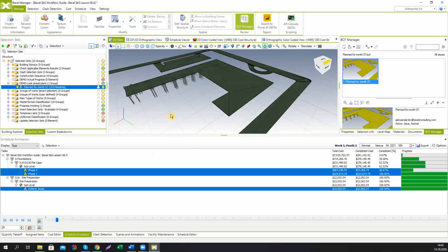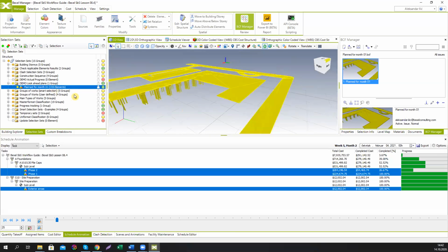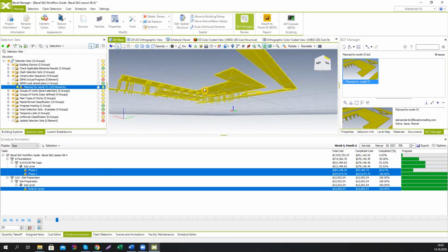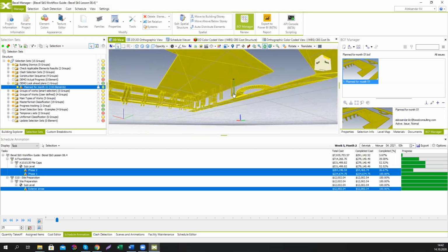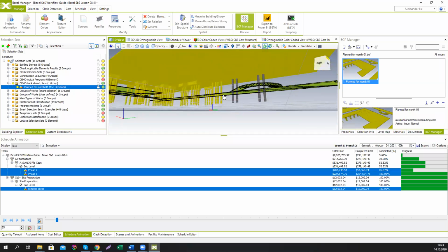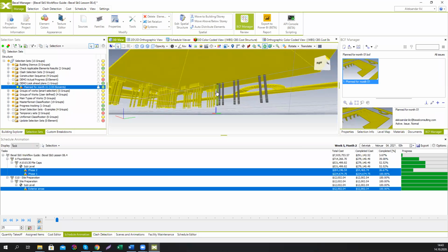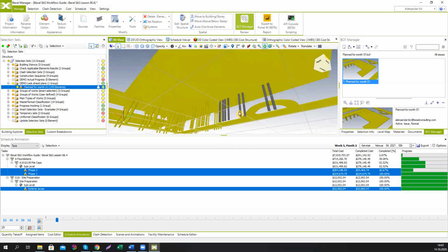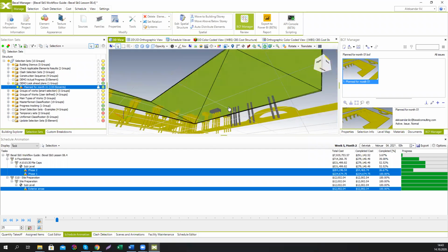So when your supervisor on site receives this selection set, he just has to open this BCF file. He will have these elements selected, and he can just uncheck the elements that were not executed during this period for this reason or that. Or on contrary, if they were performing very well, he can add new elements that were executed during this period of time. Here we're going to just unselect few of them and say, okay, these elements were executed, these not.